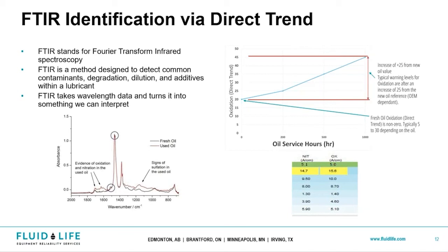But using wind as an example, you're going to spot oxidation and other acidic byproducts based on reactions with them. I always think of Dr. Seuss in his old books, and if you were a tribologist, you'd probably draft a book on FTIR and call it Ox, Nox, and SOx, right? You're going to get values of reaction with oxygen, which is oxidation, or ox; reaction with nitrogen, which is nitration, or NOx; and then reaction with sulfur, which is SOx, right?